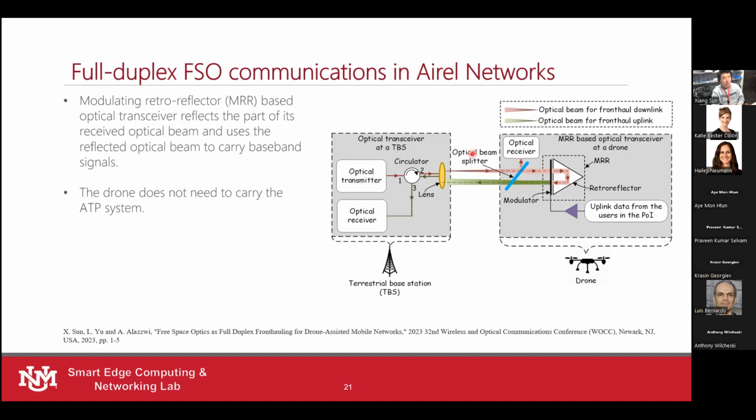Some papers use FSO to transmit energy and the data stream simultaneously, but they need to increase the transmission power of the optical beams a lot. Right now, the transmission optical power in our example is normally like 5 milliwatts, maybe even 1 milliwatt, which is not enough to transmit energy. Once you receive less than 1 milliwatt of power at the receiver side, it's really negligible.